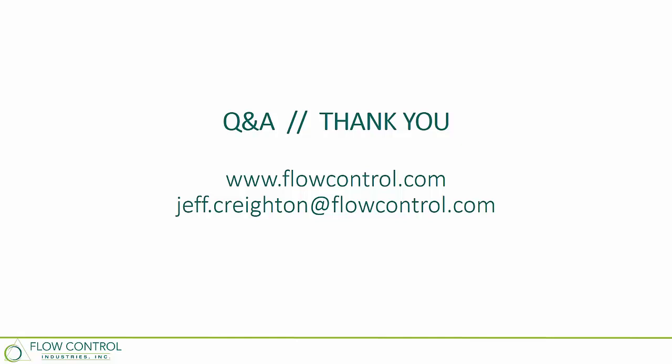A question about what kind of control technology are we using? All of these projects, we're using our DeltaP smart valve and our Flow Energy Surge platform for monitoring and information and insights around the energy consumption. We integrated with the existing control systems, so we worked with Siemens on one of the campuses, an Allerton system on another one, and a Honeywell system on a third one. So we're really control system agnostic. We were able to integrate with each of those. In some of the cases we operate with some of our own local control strategies where they had some issues with their existing control systems, but the majority of these are operating under the same control strategy, leaving air temperature, discharge air control, using our DeltaP smart valves to provide that stability with the additional instrumentation that we're getting from the smart valve.